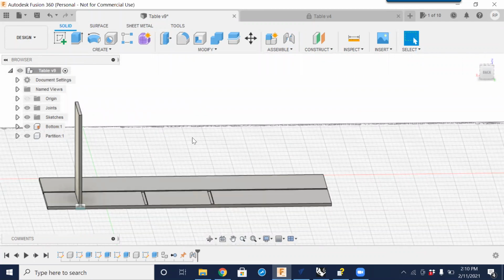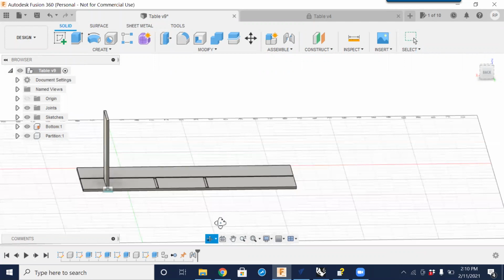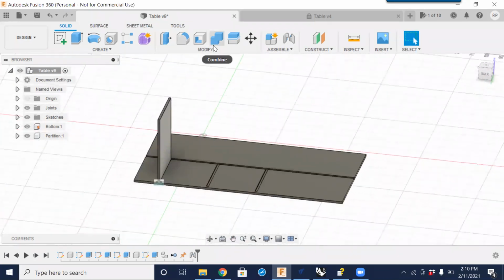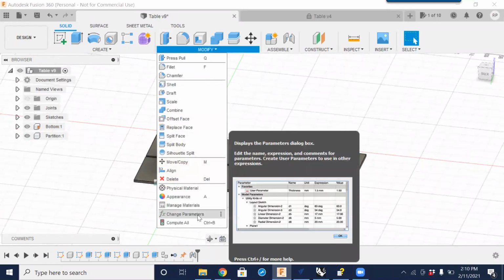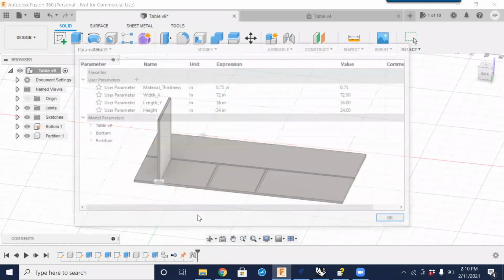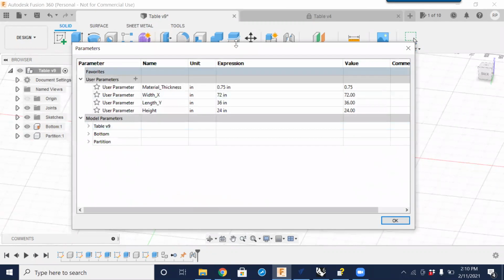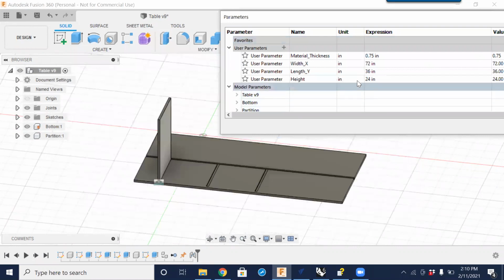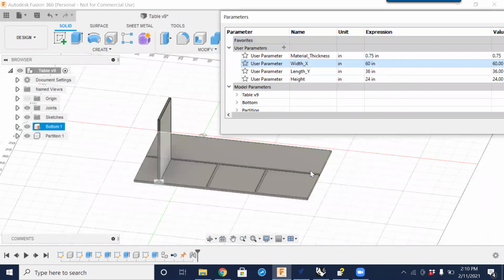And with our dynamic components that we've created, well, actually it's a word from SketchUp, within the change parameters, we now have, I'll use a SketchUp term again, dynamic components, to where we've modified and changed all of these. So if I want to modify the length of this, rather than it being 72, again, we come in and make that 60.